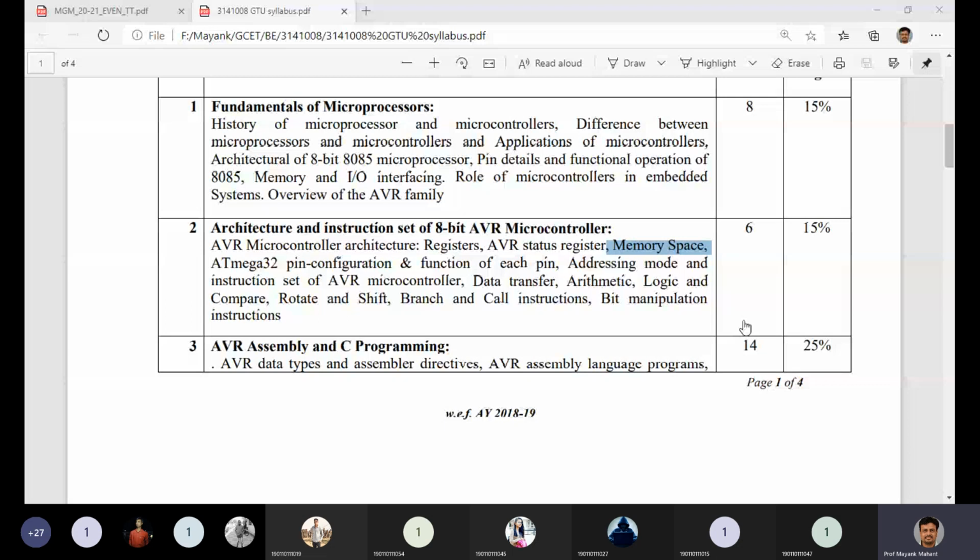With that, we also have another memory which we call an EEPROM. Basically, if we talk about a microcontroller, we need to see three memories: what is available RAM, what is available ROM, and what is available EEPROM. EEPROM is just to store some lookup tables, serial numbers, and all that. ROM we also call flash memory. Why it is called flash, I'll discuss as and when the time comes. The amount of flash helps us know what length of code you can write into that particular microcontroller.